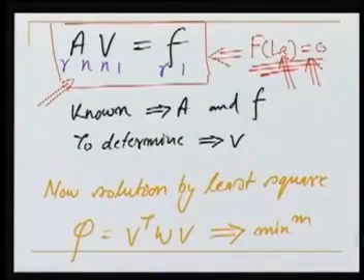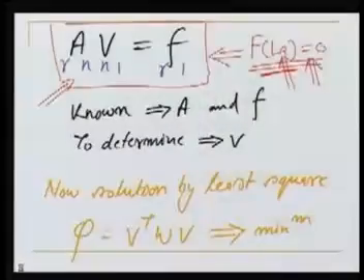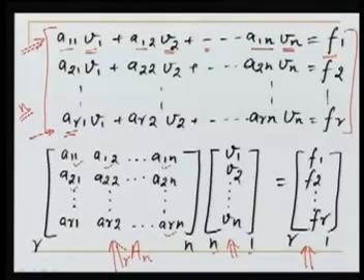And then, because we know LA is LB plus V, observation plus the residual, we put in that condition equation LB plus V, and then we expand it. And from there, we get our final model of the form AV is equal to F, where V, as we have seen, is a matrix of residuals, A is a matrix of coefficients, and F is a matrix of constants.